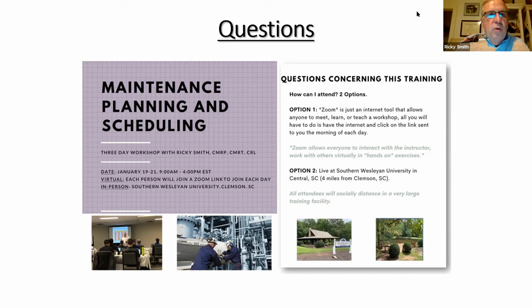Another is, how much am I putting in preventive maintenance? How much am I planning? How much am I scheduling? Even though the numbers don't look good, let's start measuring the right things in a reactive environment. That way, as we move forward, we can see the changes that are occurring. But you won't do that without having processes in place and without having someone to make sure the data is going in, those work orders closed out, going in the right fields. And that's something the maintenance planner has to do.